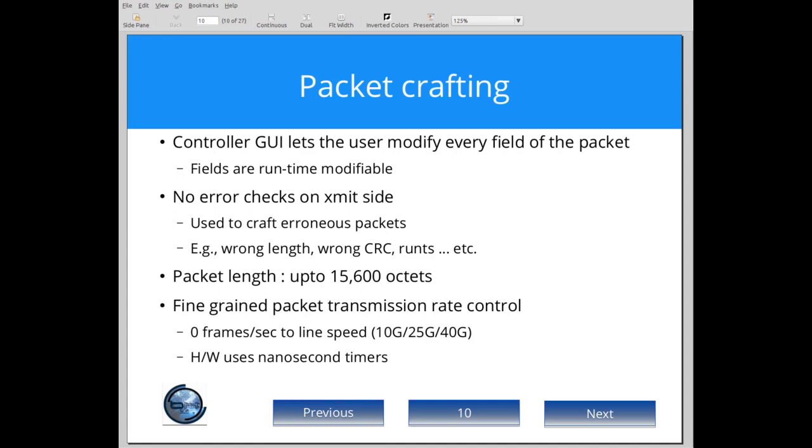One of the most important features is the ability to introduce erroneous packets, which are vital for testing the PHY, MAC, or driver capabilities of the DUT. For example, if the DUT hardware has the ability to drop packets with sizes less than a specified packet size, the developer may be interested in programming a wrong value for an IP packet length and checking how the DUT's processing engine behaves under different error cases. Thus, the packet generator's ability to set fields even to incorrect values becomes very important.